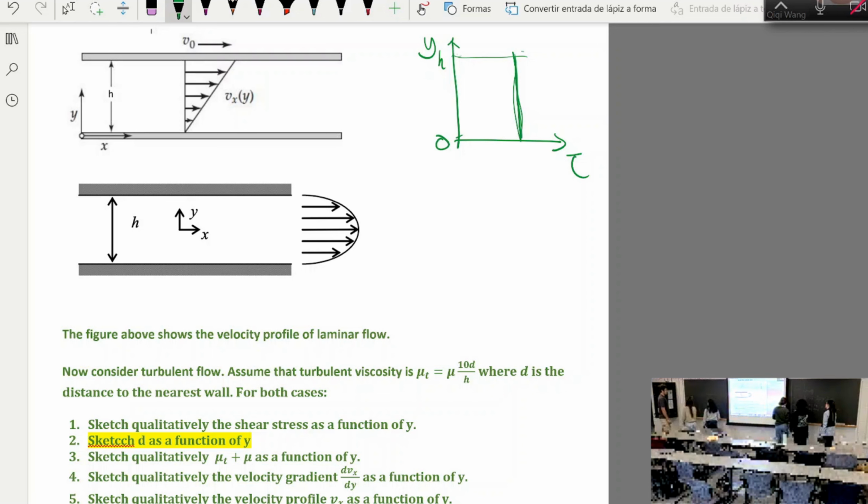There's only shear force, no pressure gradient. Questions? And the flow is the constant velocity. Yeah, this is right. This is the distance, right? The distance would be 0 and 0, but maximum over here. Yeah. The only forces are shear forces, and so tau on this face has to equal an opposite tau on that face.